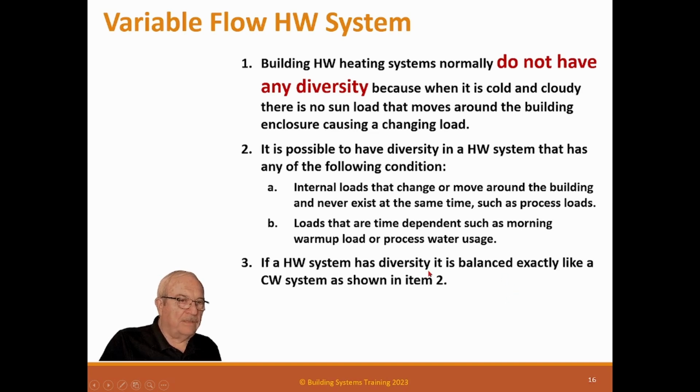So basically, if your hot water system has diversity, you need to ask the engineer, are you sure you have diversity? And if he says yes or doesn't answer, a lot of times I've found this is due to mistakes. Somehow or other during the process of the job, changes were made and they weren't picked up in the schedule of either the coils or of the pump, because there really shouldn't be any.